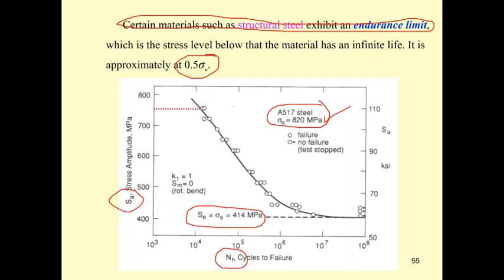The SN curve that you produce also provides the fatigue strength. The fatigue strength tells you how much repeated force the structure can take. For example, if you design the structure with a stress of 750 for this material, it is going to take about this many cycles. This one is a log scale. If you read across like this, that is going to be about 200,000.